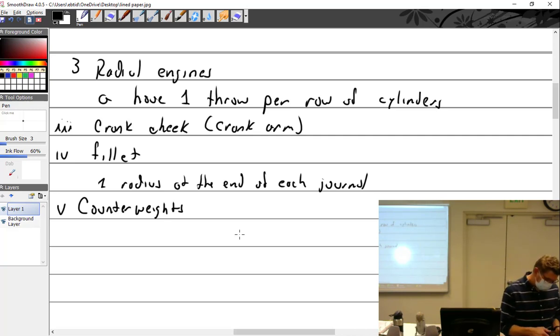So the other problem is how they're assembled. You know how people are, not us, but other people. And they just look at that and go, well, how hard is that to figure out? You got a plate, you got a snap ring. You put the plate, you put the snap ring in. Well, the snap ring's got a right way to go in and a wrong way to go in.